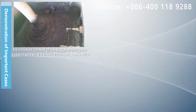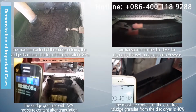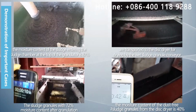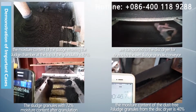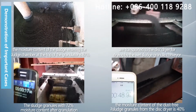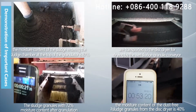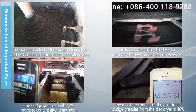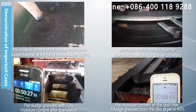The particles after granulation have a water content of 72% and are transported through a conveyor to the vertical disc dryer for further drying. The dust-free sludge particles after drying by the disc dryer have a water content of 40% and are transported by the belt conveyor to the sludge storage silo. As we can see, the sludge discharge is in good and stable working condition.